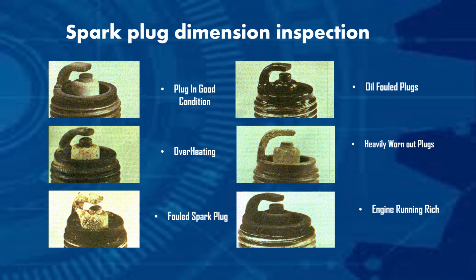Engine running rich. Too rich is indicated by a powdery black coating. This indicates that the plug is firing but far too rich. Check chokes and carb float levels before you go jetting up.